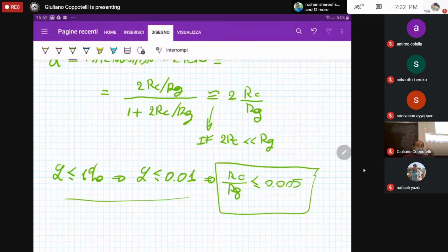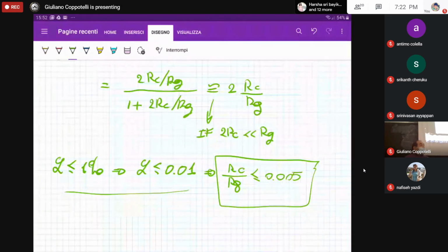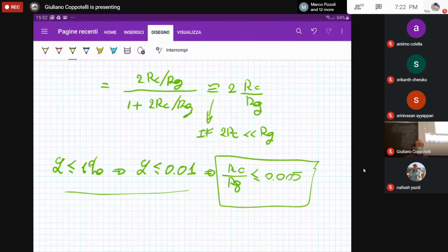So if you want to start a measuring campaign in those worst conditions, for example the operating jet engine, and you would like to have an attenuation of the cables less than 1%, then you have to be sure to use connecting cables or strain gauge resistance so that that inequality is satisfied. How can you choose that?